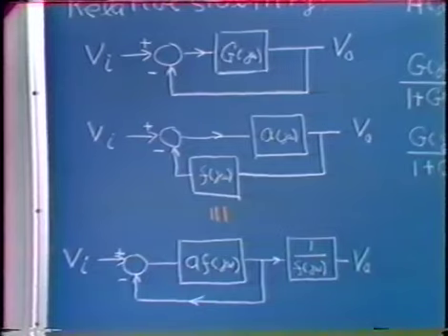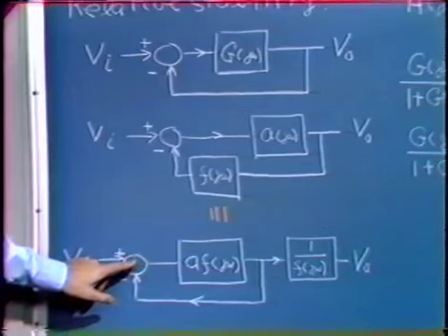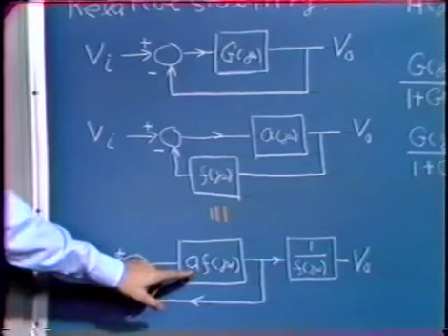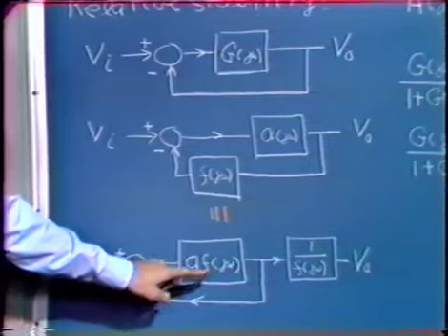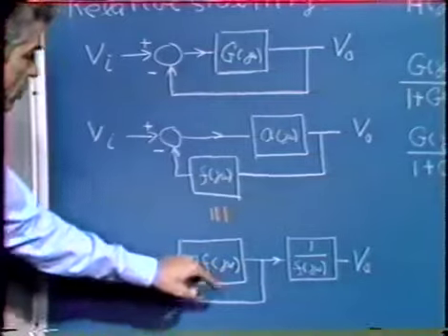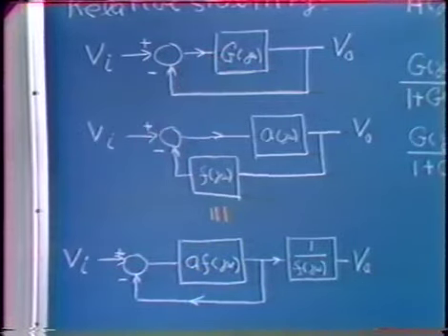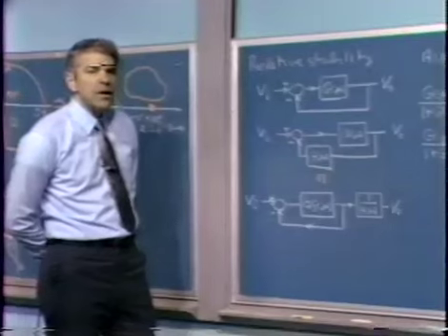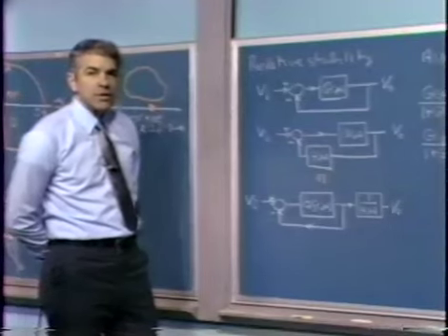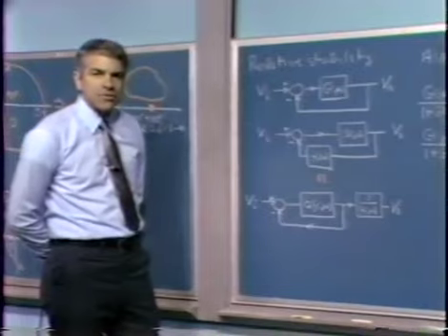We found out in a root locus sense that stability depends only on the AF product. Again, when we base our stability analysis on frequency measurements, we're only really concerned about the AF product, and we can determine our stability information from this portion of the block diagram, correspondingly this one. So what we'd like to do is look at the behavior of G over 1 plus G, where G is a function of j omega.